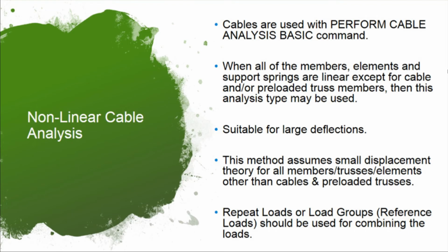Repeat loads or load groups should be used for combining the loads. You should not use load combinations. Load combinations will give wrong answers for nonlinear analysis.